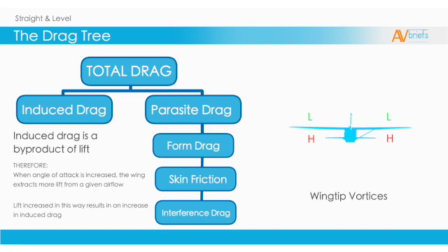So by introducing winglets, engineers are able to slow the mixing of air, and keep more higher pressure air from escaping into the lower pressure. They also minimize the size of the swirls, which reduces drag. That's why we've seen such a focus on winglets over the past couple of decades. By using winglets to reduce wing tip vortices, it's possible to save 45,000 gallons of fuel a year from just one plane.